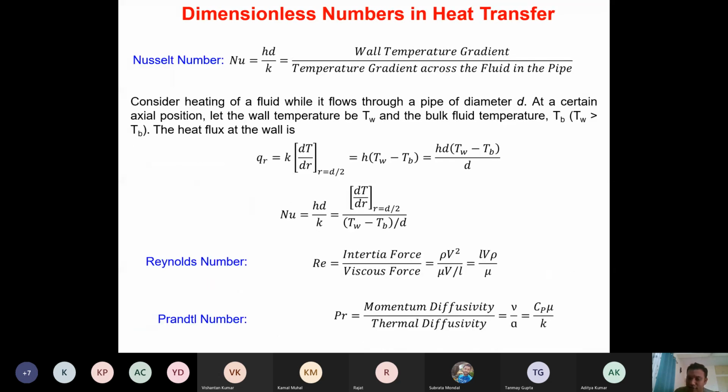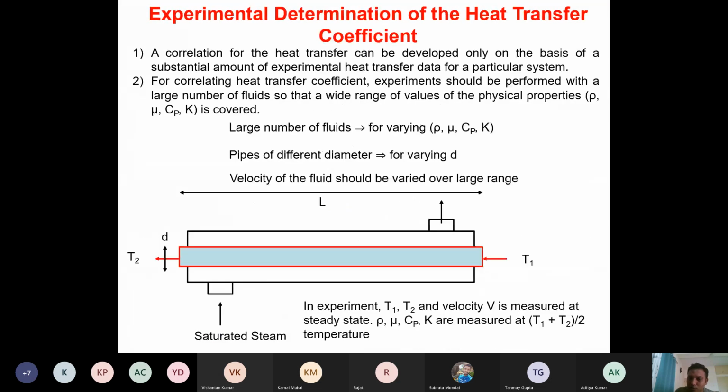Okay, let's look at what I'm trying to say here. One, the Stanton number looks at the convection taking place in this pipe, versus how fast the heat is taken by the fluid flowing. Whereas the Peclet number looks at how fast the heat is transferred through this metal wall by conduction.